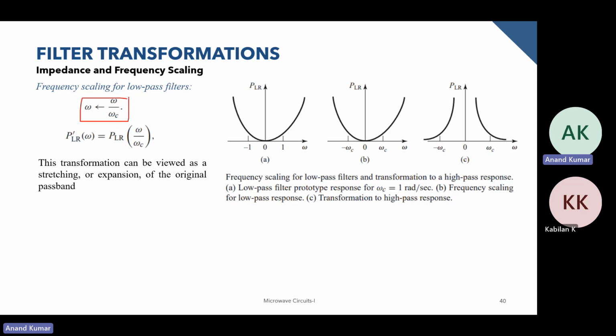So frequency scaling is done by this expression over here, and this is the plot for the power loss ratio for a normalized frequency. Once you have scaled this, it will become something like this. So this will scale to the correct cutoff frequencies.